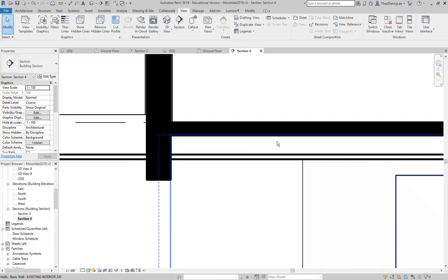In real life, when you're building something like this, do you think you need that cavity normally? Yeah, you often would want it for services, but you don't need as much as people think, especially with a small space like this. You're not going to have a huge amount of services. You probably wouldn't even have ducted air conditioning for a space like this. You'd most likely just have a split system if you're going to have it at all. Well, a shop, you definitely need air conditioning, but it probably would just be a split system these days.